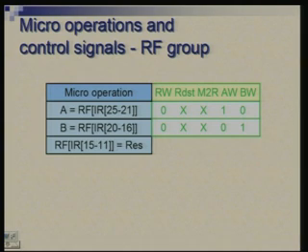Now, here it is writing into register file. So, we will make the write signal 1. We need to define our RDST. So, it will be 1 in this case, M2R is 0, and we are not modifying A and B.